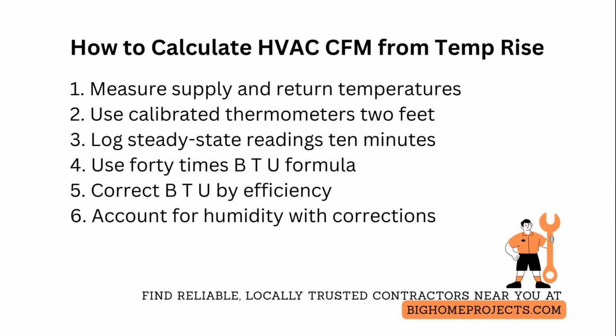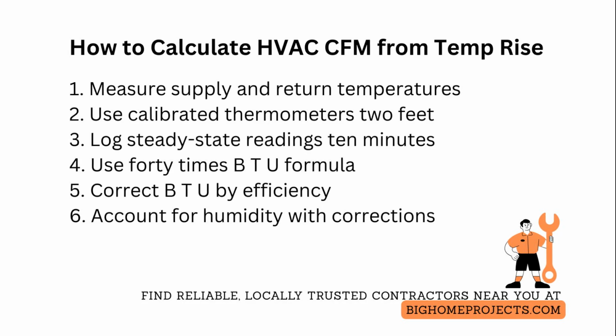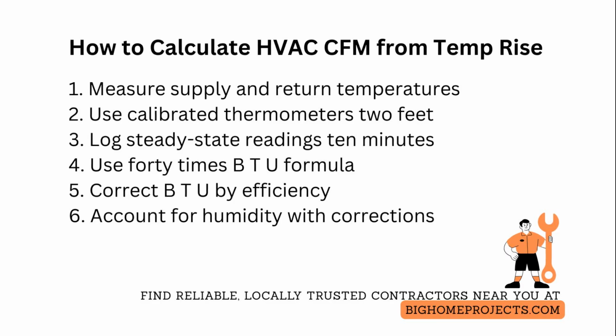For accurate register-level airflow distribution, combine whole system CFM from temperature rise with register-level velocity measurements and register area to identify balancing needs, and always average multiple readings across several minutes to reduce noise.